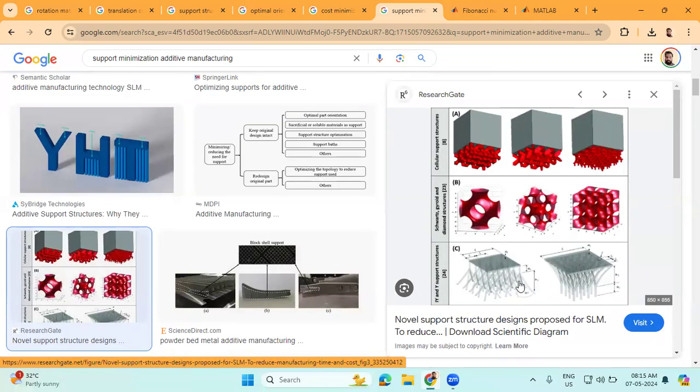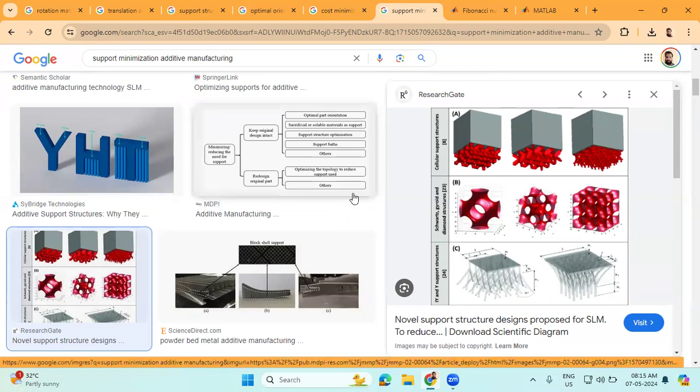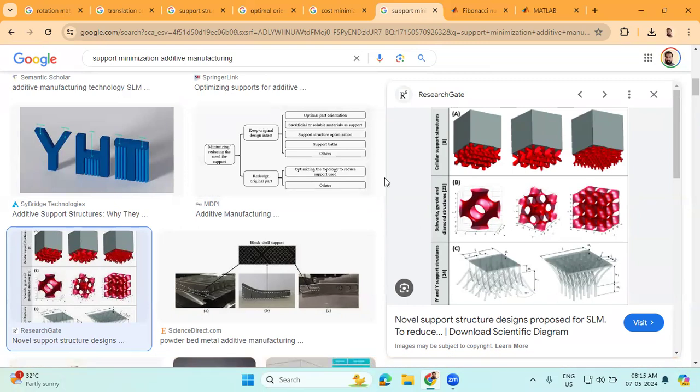Moreover, we also learned about the significance of orientation in the manufacturing process, especially in additive manufacturing. The orientation of the object during the printing process can significantly affect its strength, quality, overall performance, and overall appearance. We also explained that choosing the right orientation is crucial to achieving the desired result. Finally, we explored different models used to optimize the additive manufacturing process, such as cost minimization and support minimization. These models can help to reduce the production time and cost while achieving the desired result.